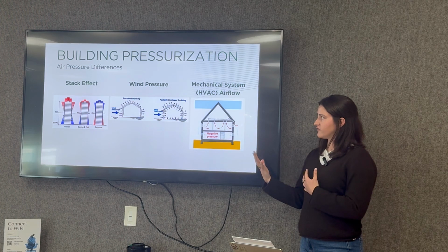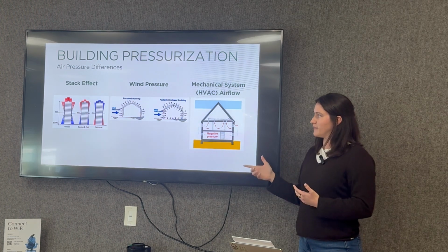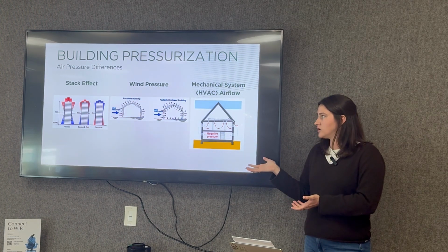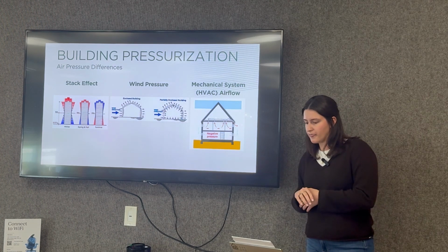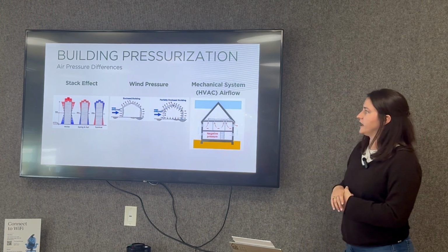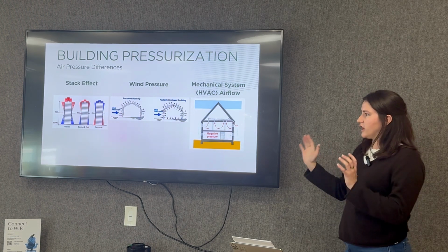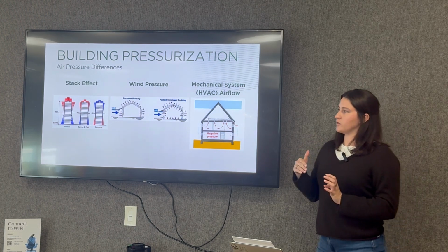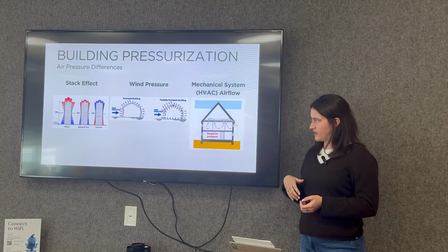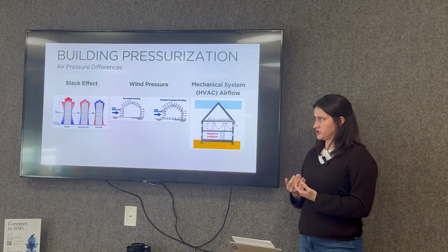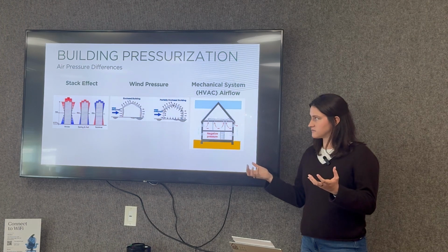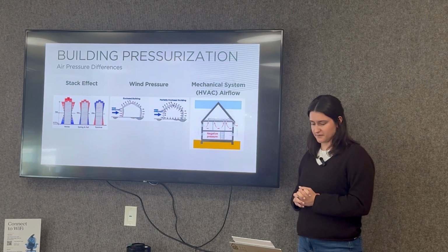Wind is airflow, which then translates to dynamic energy applied to a building roof or wall, and pressures felt by the building vary, obviously, per elevation. If you're on the coast, you're going to get a lot of wind on one elevation versus the rest of them, which is going to affect how the air leakage leaks at your building.